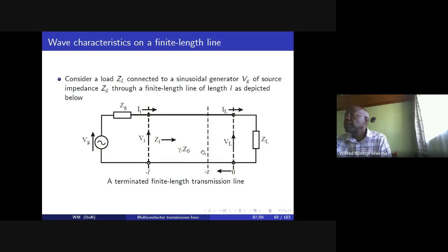So it's given as L. What I've done here is that I've rearranged my coordinate system and shifted it to the output port so that z increases positive to the right, while it becomes increasingly negative as we travel towards the generator. So that ZL is terminating that line there.